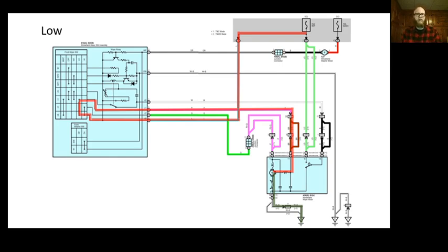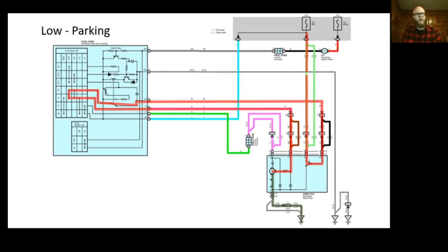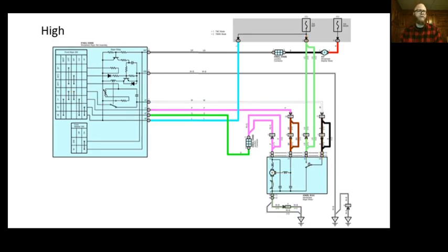When I go to park it and I turn off my wipers, then my park circuit engages, and still that's going to be through the low speed brush. Part of the reason they make it through the low speed brush is they use this for the washer function as well, but also so that it's not moving so fast that momentum causes us to travel past that park position and the wipers would continue on traveling. Not likely, but possible.